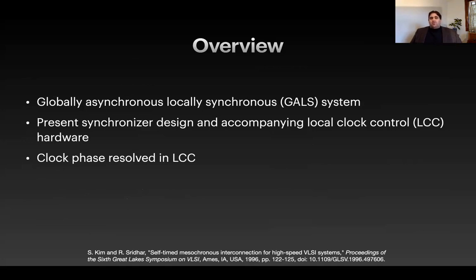And the authors are going to give us a synchronizer design that also has an LCC, or local clock control. That is the block that's going to resolve the disagreement in phase between these two asynchronous blocks.